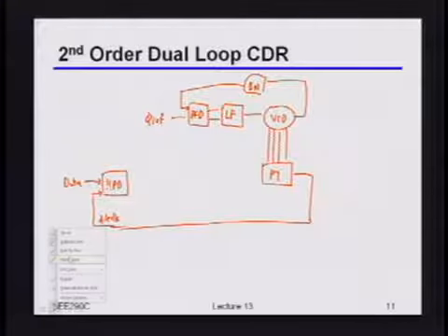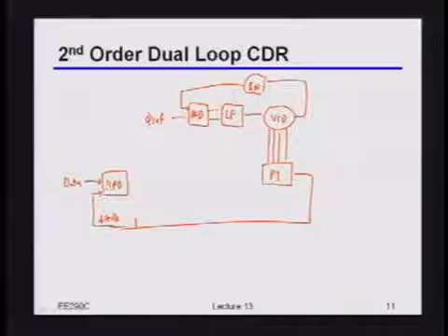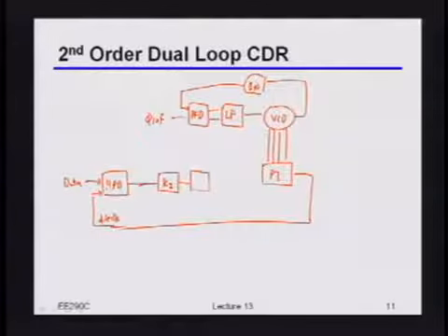But now, as we said, instead of making this loop filter have only one integration in it, I'm actually going to have two integrations. Okay, so let's draw what that would look like. For reasons that will hopefully become apparent in a second, let's say I put some gain. Then I accumulate the thing once. I accumulate the thing again. And then I feed it to my phase interpolator.